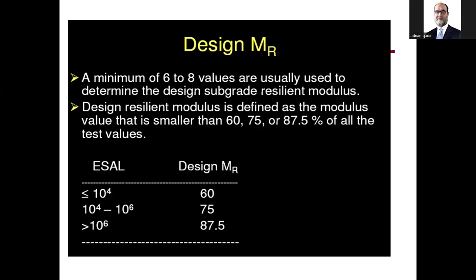Conventionally, we take around 10 locations or 8 locations to perform this, though the specifications are very different. What does the specification say? Say you are doing a 10 kilometer road. The first test pit will be at zero station, and then the other test pit at 100 meters. Calculate the value between 0 and 100 meters, classify the soil, and see if there is much difference.